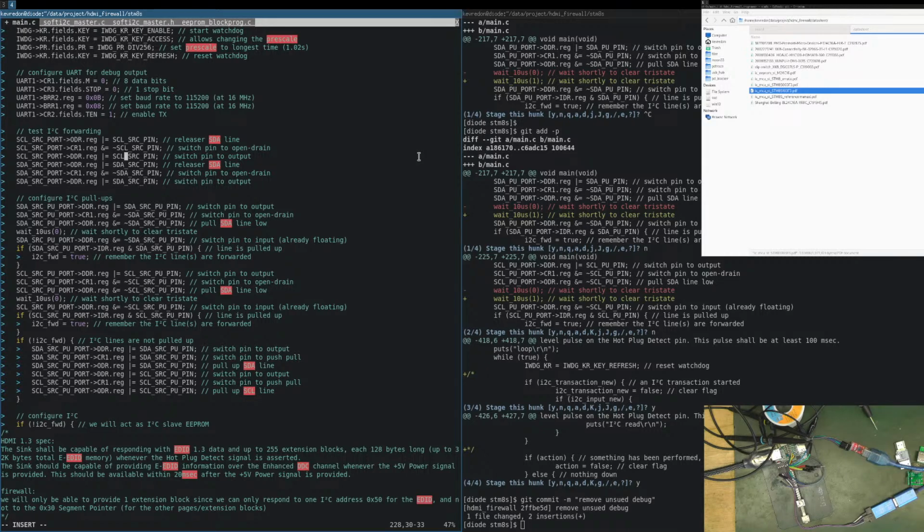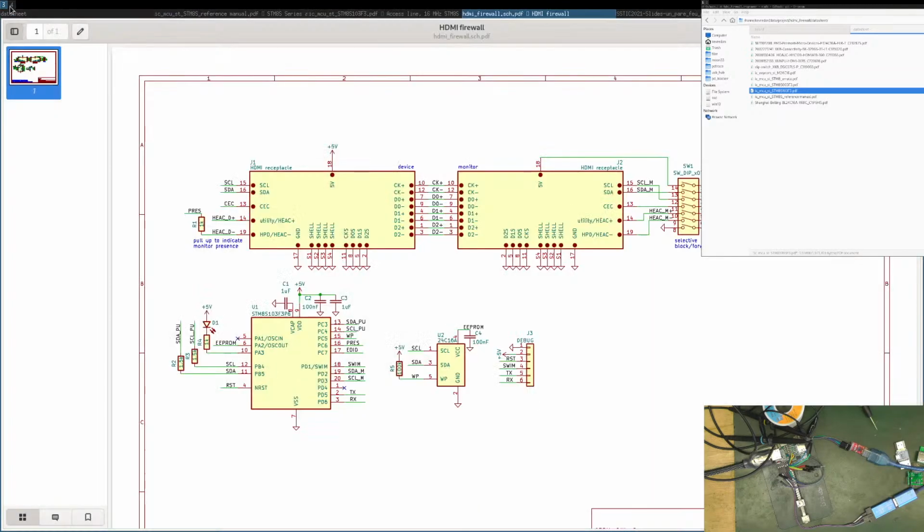I can detect if the monitor is connected or not. That's good. This is another thing. So I had a problem is that I can't detect if it's connected or not, I can't in all cases. So the issue I had is I will read the monitor over the I2C, but it only works if it is connected. So how do I check if it's connected?